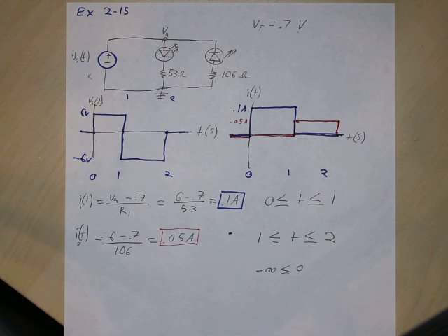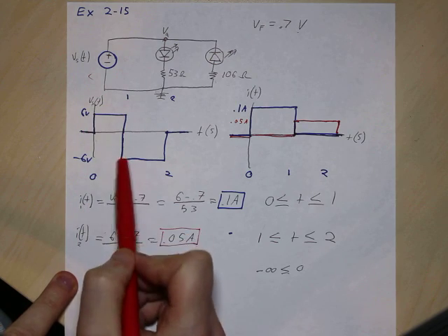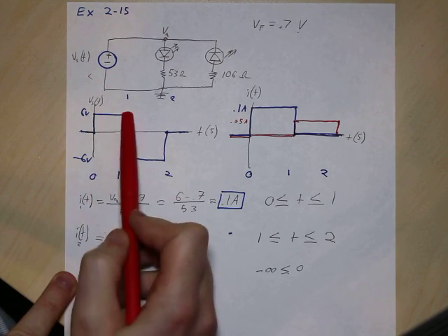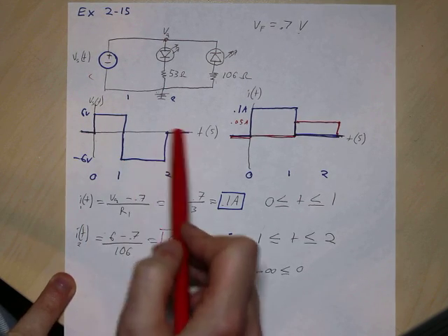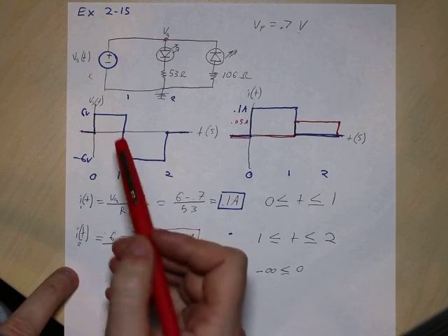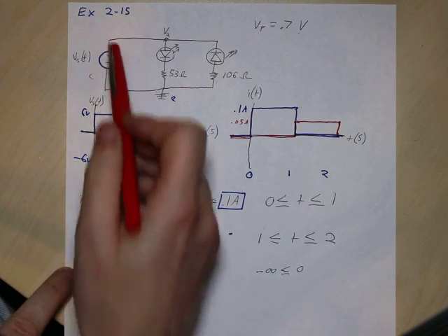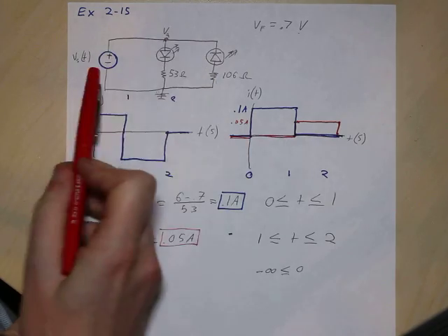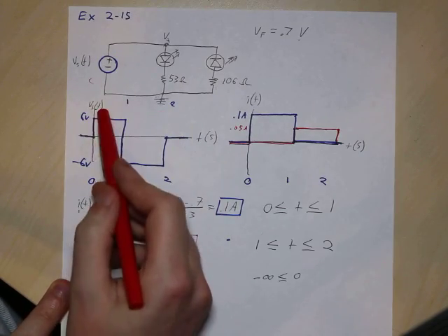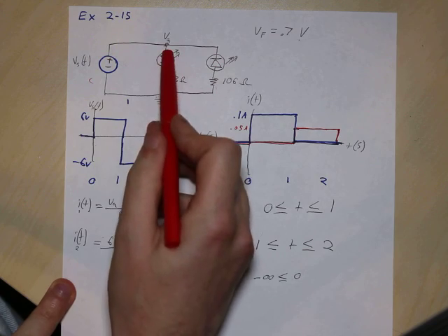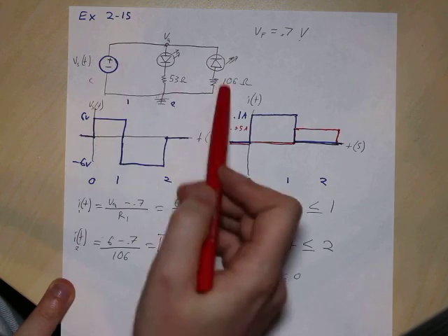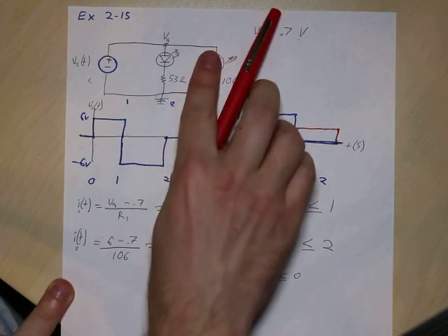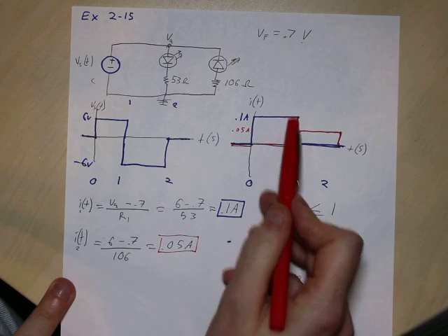That's kind of a cool problem. I like that. So let's just recap then. New pieces of this one, square wave. Instead of just having a constant power supply, we gave it a power supply that changes. And we call this a square wave because it approximates a square, and it's a really nice mathematical way of calculating it out. Because it's a square wave, that means a positive and negative switch, because you have a negative voltage here, which means this whole power supply switches around. When this switches around, no power can come up through this. When this is in the first position, power can come down through this, but nothing can come up through here. So that cuts that part off. And that's why we get these two different currents.